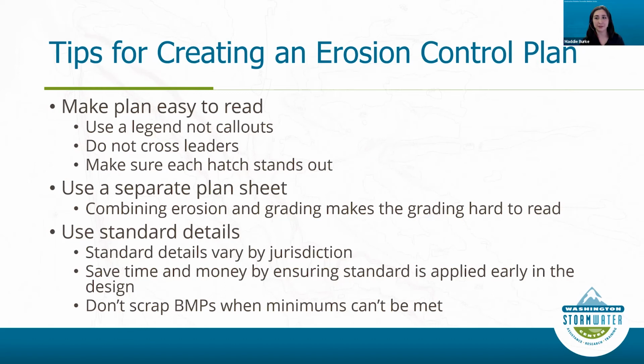And then another thing about local standard details is just because a BMP can't be met doesn't mean you should scrap it entirely. If there's not room for a 100-foot construction access, that doesn't mean you should avoid it when you could negotiate a 50-foot construction access. So consider how you can incorporate BMPs when those minimums can't quite be met at your site.